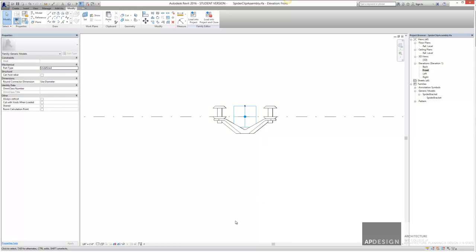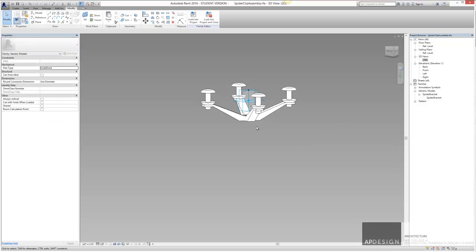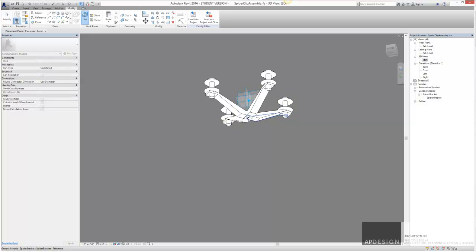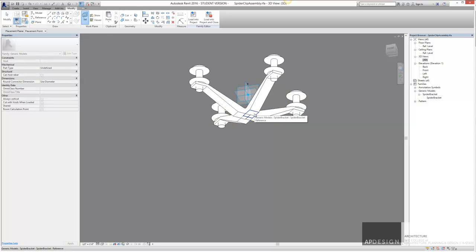Okay. So the next thing we need is to create a bracket. So let's imagine there's structure out here. We need some kind of rod or tube or some pipe kind of connecting that. So let's create a pipe or a tube. Alright, so I'm going to set my work plane as, say, down here, and I'm going to create a circle.